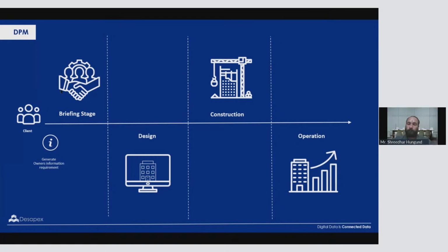Right from the programming stage, we work with the owners to identify project requirements and set up framework as per ISO 19650, identify project expectations from each stakeholder, the information requirements, the granularity and the timelines involved. Setting up platforms to perform project management, clash detection and coordination with design elements, model audits, validating cost and timelines of the project are all part of this service.